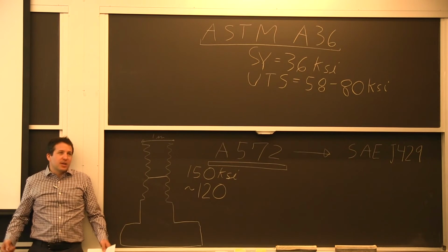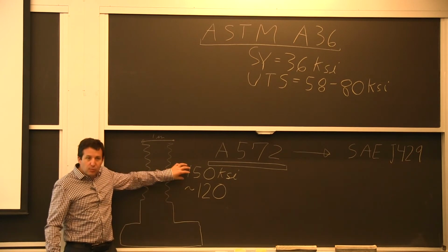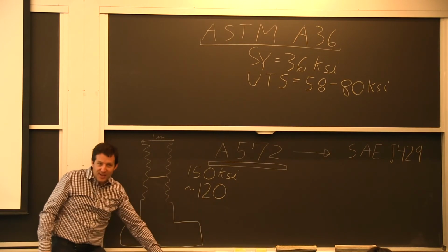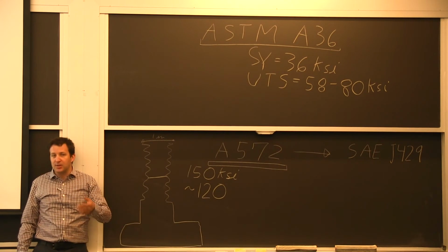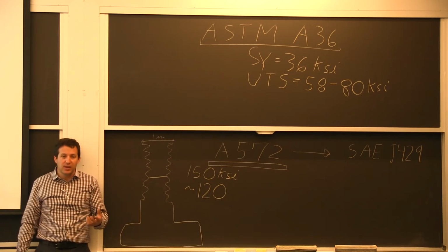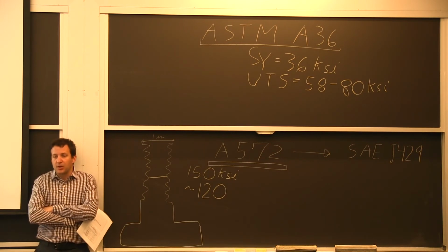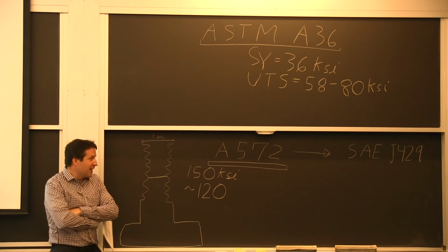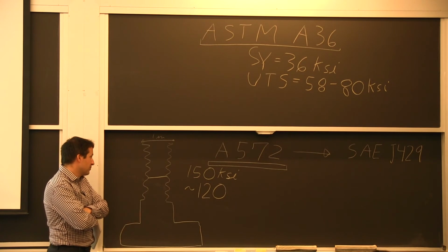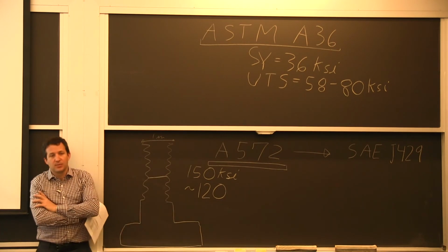Now, if you reduce the yield strength from 150, it will reduce that 10 KSI to 18 or 13 or whatever it is. So you still care about the initial yield strength because that's what prevents you from initiating cracks, if you have seen that part of material strength. But you're not getting exactly what you could think you're getting when you're looking at these tables.